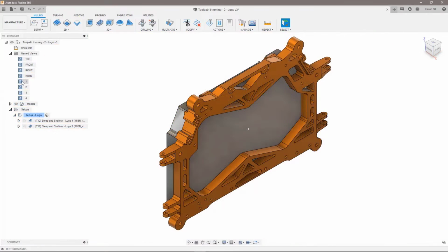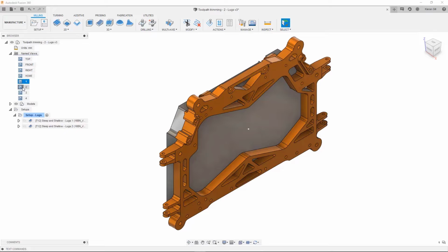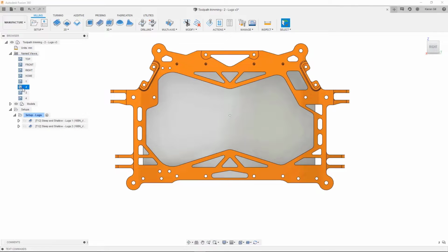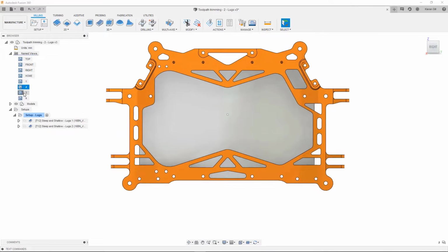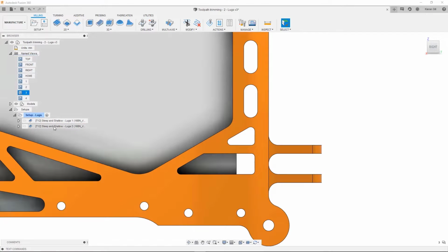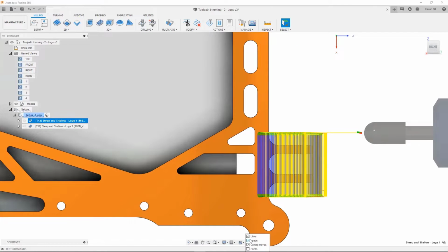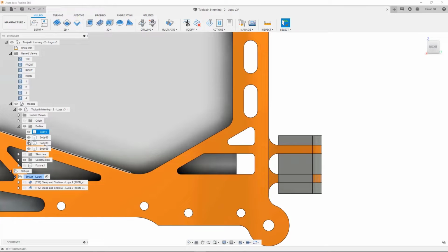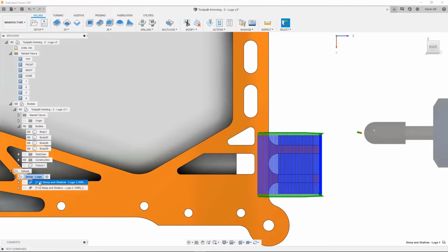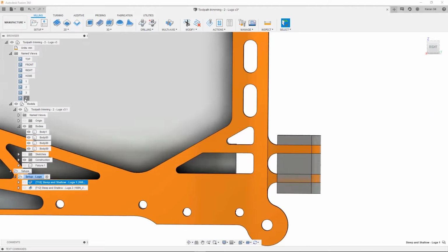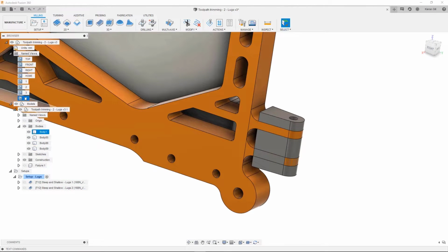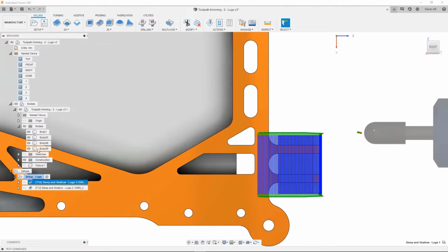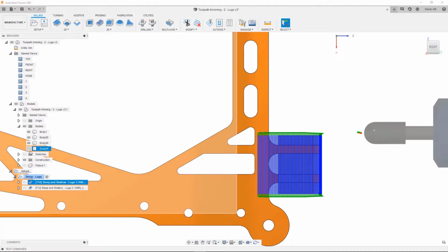The second model presents a situation where we may want to remove inefficiencies in the toolpath. In this example, I'm trying to machine the lugs with a tool approaching from the side without rounding off the sharp aspect of the lugs. To do this, I've constructed some geometry to help get a good quality toolpath across the two lugs. However, this resulted in an inefficient strategy with loads of air cutting. Toolpath editing allows me to trim away the excess I don't need and keep only the portions that are required to machine the lugs.